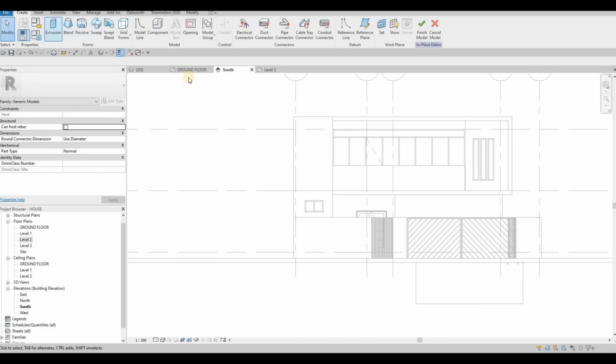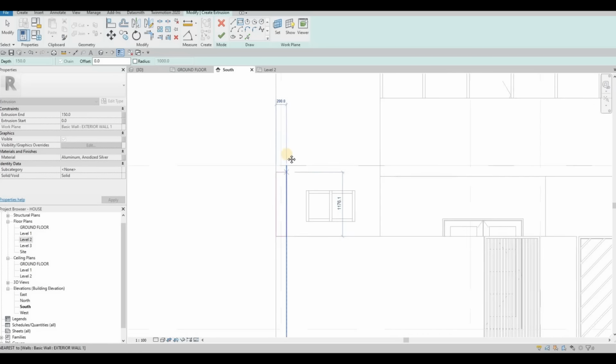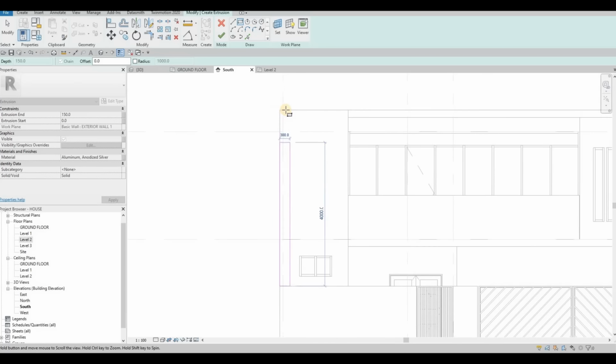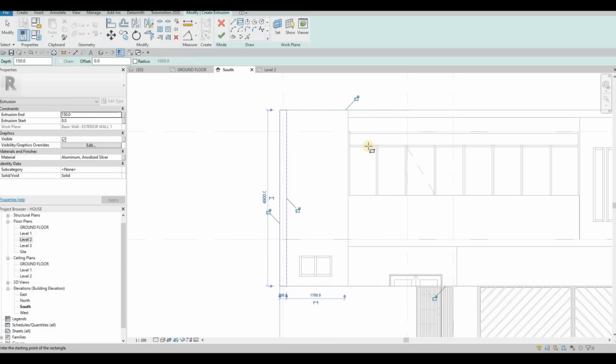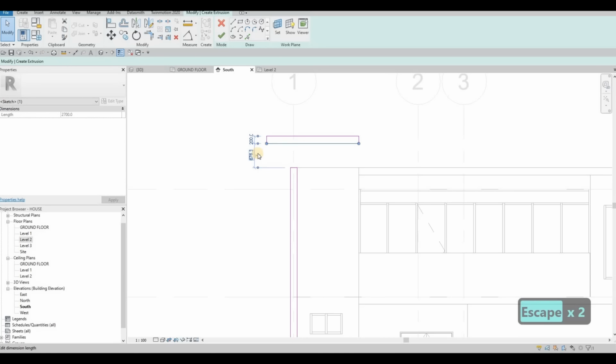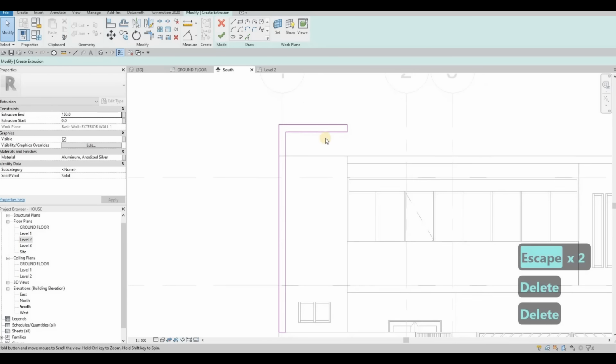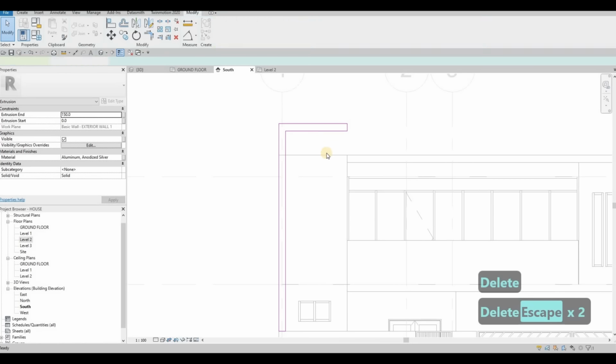and then here we're gonna do an extrusion, pick a plane and select this wall right here. I'm gonna do it from here, from the border wall, and then I'm just going to put it a little bit at the top. So I think around, yeah, around 700 at the top. Trim and extend right here. And then delete the unnecessary stuff, the lines right there. So click finish.